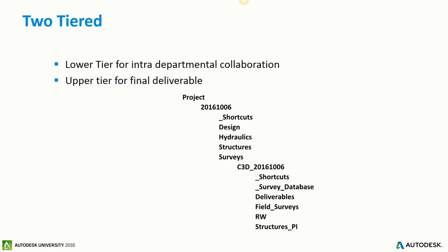So here's the problem. Imagine this. This is very specific to how they're working in the survey department. But the survey department works and creates multiple surfaces that are their own. They don't want to share it with anybody. For example, they have an aerial topo done, and that's a surface, which is photogrammetry, then they do a real survey, which is more accurate. They mesh it together. That's the final deliverable. They want to give the final deliverable. But you cannot get to that point unless you create shortcuts. If you create a shortcut, well, both those inaccurate surfaces are also available to everybody on the project.